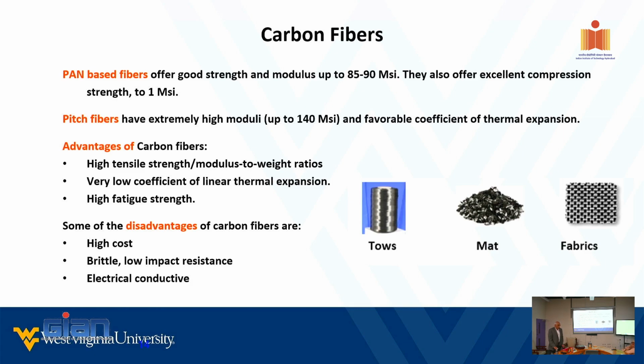Just for the benefit of the audience, one thing that we are observing: as you're right, we have a long coastal line. Second thing is, even if you're not close to the coastal line, for example cities like Hyderabad and even the NCR region in Delhi, they have been using groundwater for construction. The groundwater, if you're not very careful, has a lot of chlorides. The chlorides are infused into the concrete, then the corrosion starts. It's a big problem there.